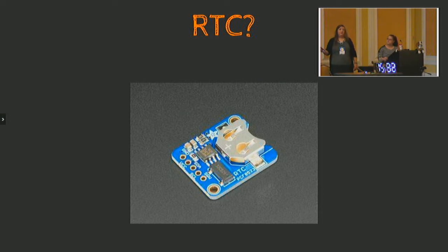Some of those also are able to store an offset, because precise as it may be, an RTC module is sensitive to temperature and things like that. And so they might go off course by maybe 1 second a day or something like that. And so depending on the model, you can store that offset and say every day go back 1 second.